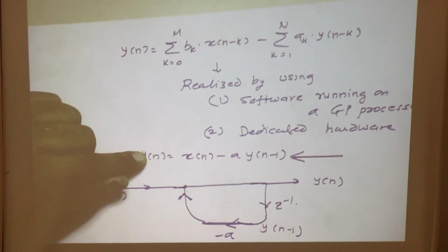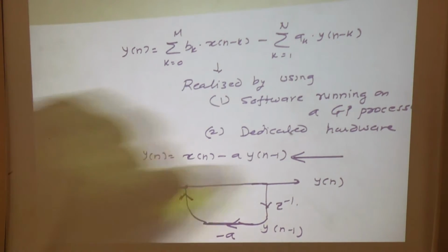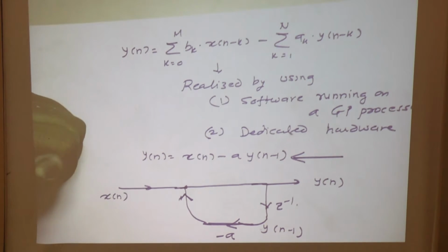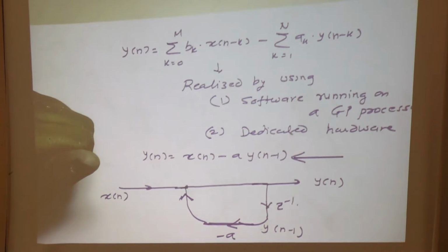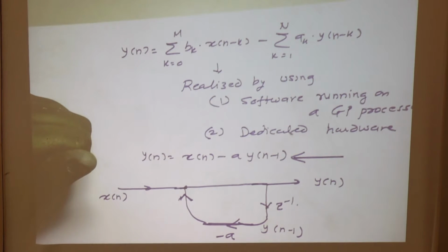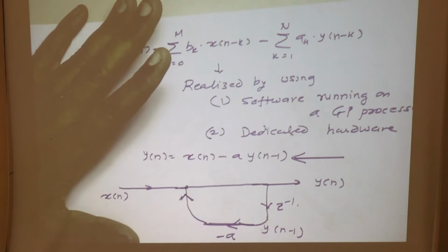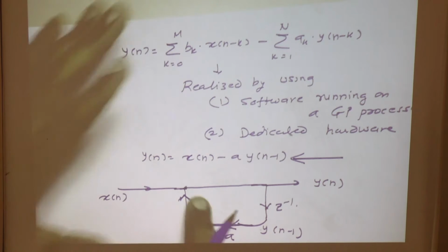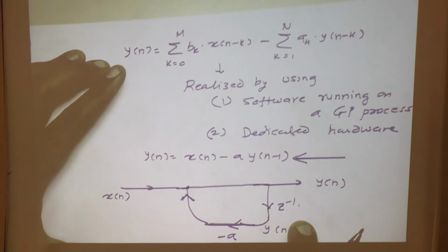Alright. What is hardware realization? Put an adder here, assuming that all is floating point, take a floating point adder. These are devices like RLC that are available on the shelf. The adders and multipliers in the form of integrated circuits are available on the shelf. Pick them up. You pick up an adder, 16-bit or 32-bit, pick up a 32-bit multiplier, interconnect them like this. Pick up 32 parallel flip-flops.